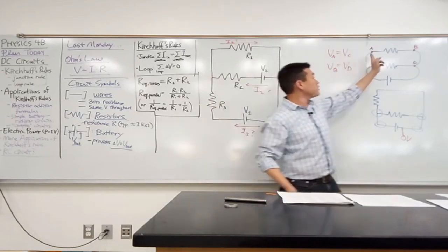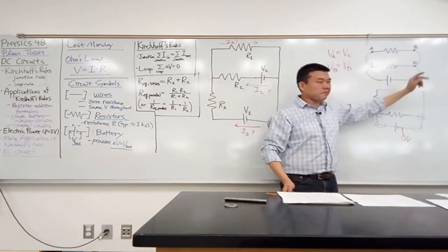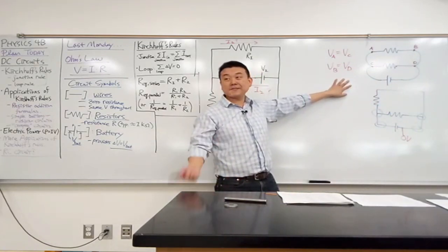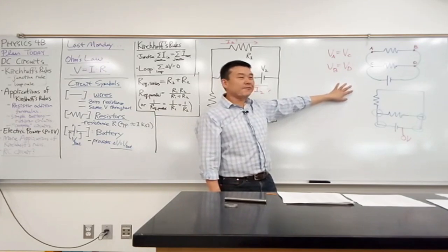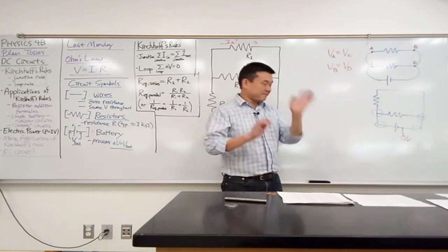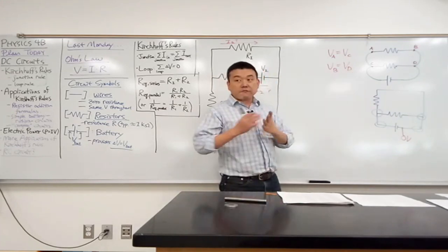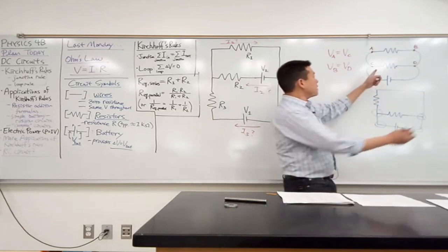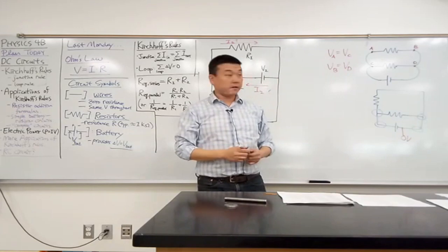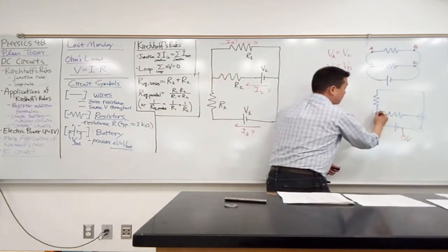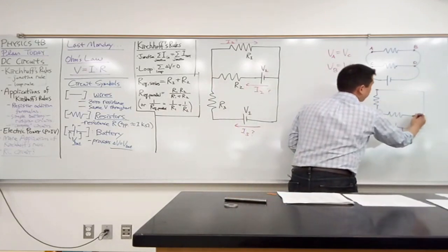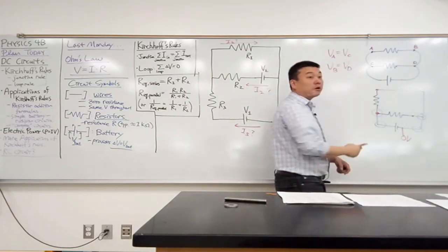I mean, in this particular case, what Kevin was saying also turns out to be true. If this is true, then the difference would be the same also. But I want to state it this way because when you get into semiconductor circuits, deal with op-amps, there's a very strange way of making things that are parallel that are not actually connected. So when we say some things are parallel, it really means their voltages at the end points are the same. That's the definition of something being parallel. Here, the voltage at this end point is the same because it's the same end point. And voltages at these two end points are the same because they are connected by a wire alone.